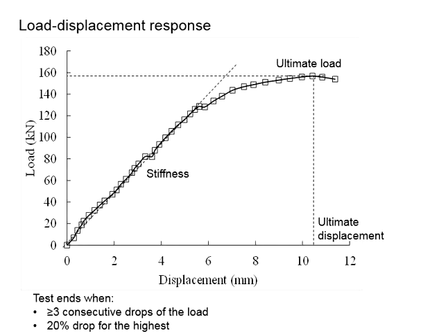For you to determine the maximum capacity of the specimen, you will seek the highest loading achievable by the specimen. This is achieved by observing the peaks of the load displacement curve. Theoretically, once we confirm the peak, we can end our test. Now the question here is, how do we know when we shall stop testing? This can be determined in two ways. The principle behind it is to confirm the ultimate state of the specimen.